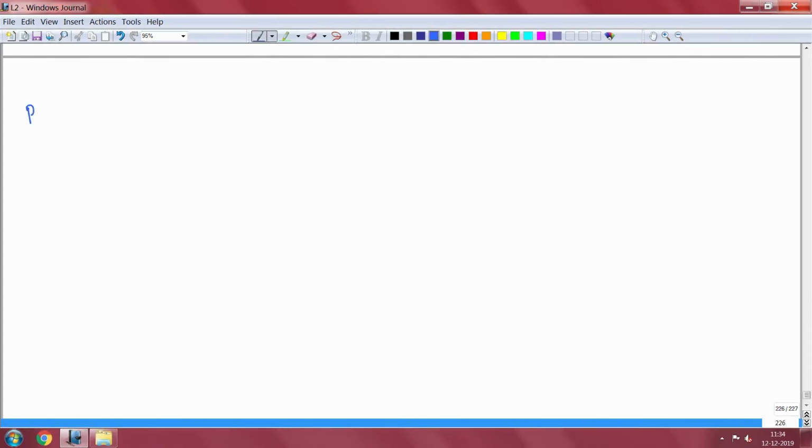But the first problem that I have designed, we want to take a look at a certain type of viscoelastic material for which the analog is already given to you. So let us say problem 1. Problem 1 is the Jeffrey's fluid element. And if you recall, the Jeffrey's fluid element comprises a spring and a dashpot in parallel, and then another dashpot that comes in series.